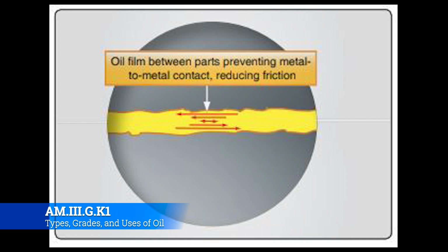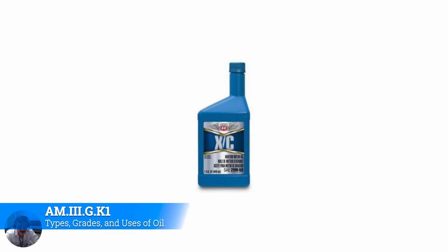Because the coefficient of friction with the engine oil is lower, and it moves around and helps cool and clean the engine, the engine can continually have very close proximity metal parts, because this cushion is very, very microscopically thin. It's just enough to coat the outside of the parts as they touch together. That little bit of a cushion allows those parts to pass in between each other in very close proximity and at a high rate of speed. All right, so this is Aeroshell 20 weight 50, so 20W50.